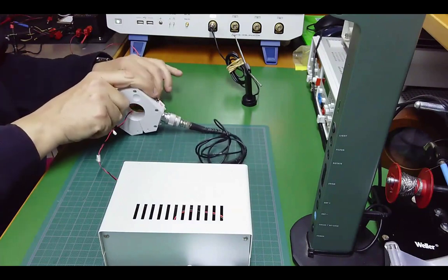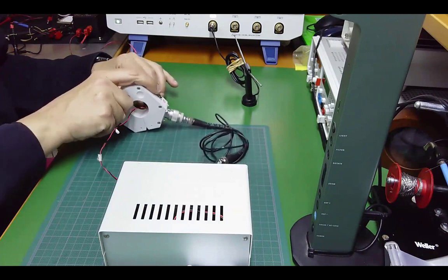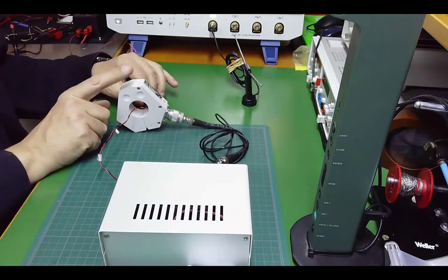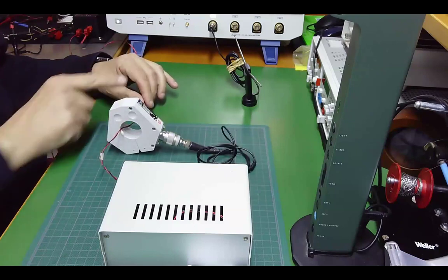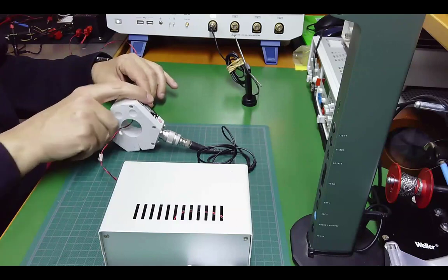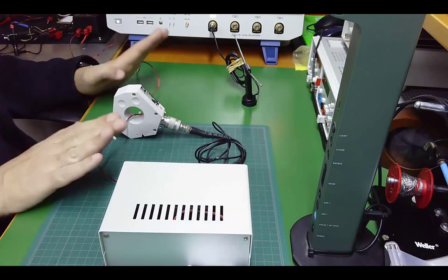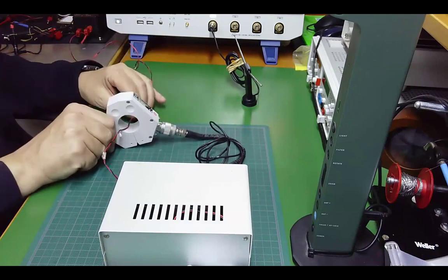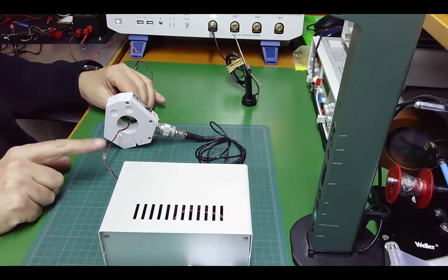If the cable is long and the frequency is high, usually in some specific positions of the cable you can identify nulls, and in other positions maximums. You have a standing wave in the cable. So it's important to identify the position that is good for you and to avoid movements. I'm going to put the probe here because in my next experiment, I will try to put a ferrite here.